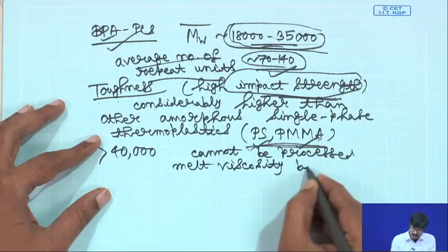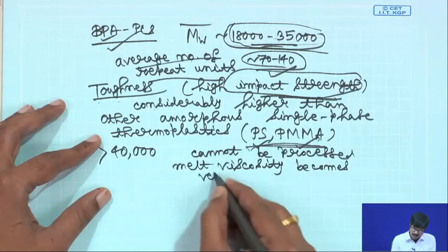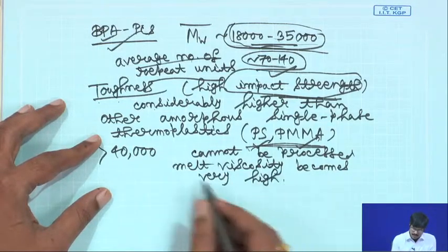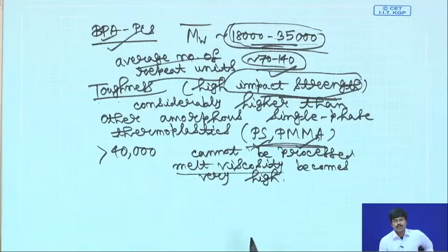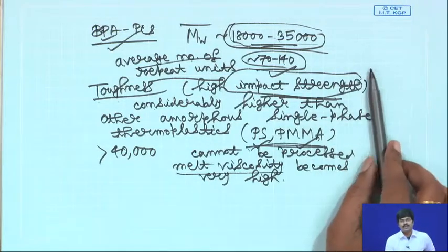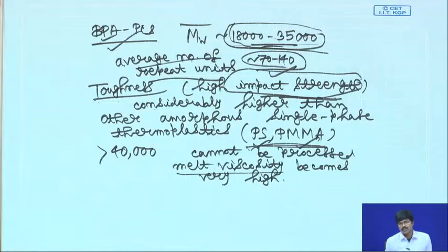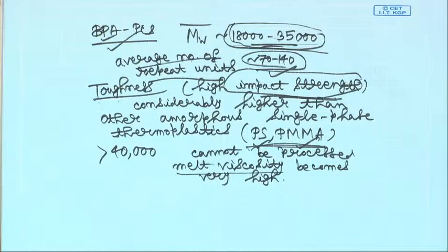You remember all these concepts are interconnected, because we talked about melt viscosity when we were talking about the melt transesterification process, and there we argued that towards the end of the reaction you increase the temperature to almost 300 degrees Celsius, not only to facilitate the removal of your byproduct phenol in order to take the reaction forward, but also to have sufficient melt flow characteristics at that temperature, because when you have a viscous melt, the viscosity drops when you increase the temperature.